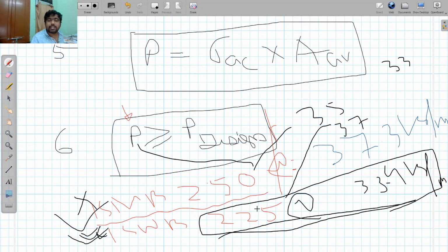In this case, the design is not an economical design, and here somebody may say that your design fails because you have to save the money. So that is also another objective of the design, that your design must be economical. Okay, so this is how we can do the design of a column. Whatever design steps I have discussed right now are also applicable in the case of a strut.